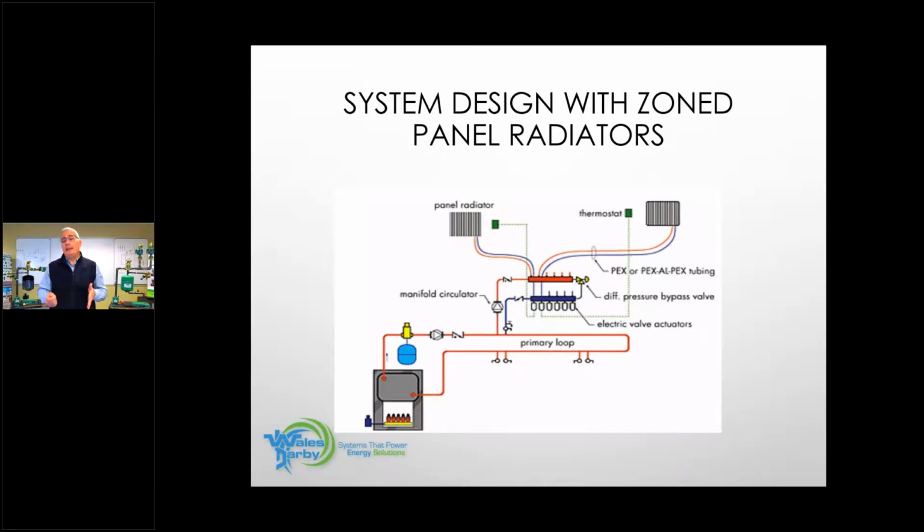What's really neat is I got balancing valves here, so I can really fine tune the flow rate. And I have the ability on the return side to add actuators. Actuators are just little mini zone valves. So I can zone on this, purge on this. Now I can run PEX pipe if I choose as my supply piping. So let's say I was going to use panel radiators, I can feed them all with home runs with PEX pipe. Right?